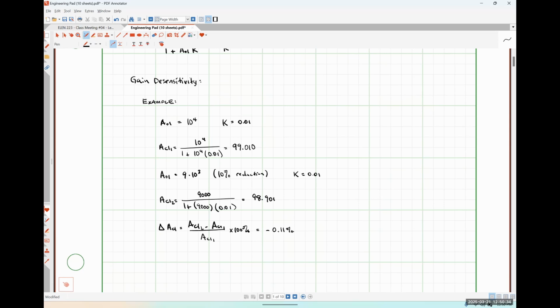So this is one of the real reasons why the overwhelming majority of op-amp circuits are negative feedback circuits. In a negative feedback system, it doesn't really matter that our very large open loop gain changes from device to device or component to component in a manufacturing run, because in a closed loop system, the gain is only going to change by some very small amount.